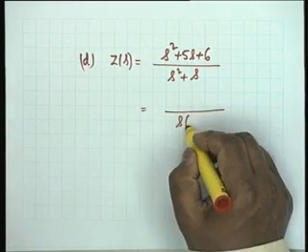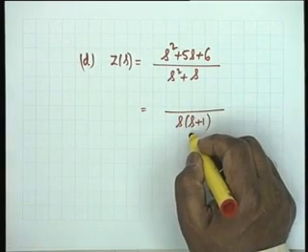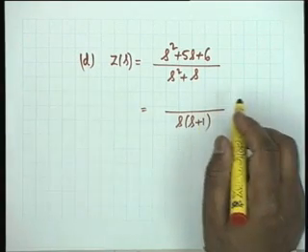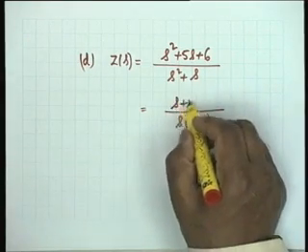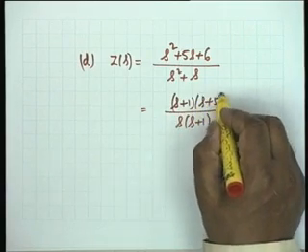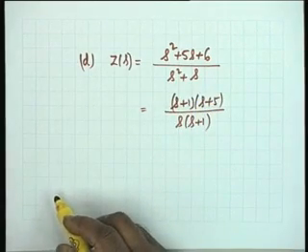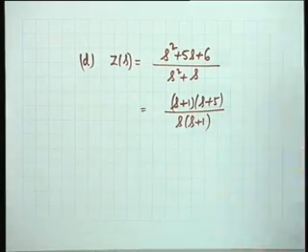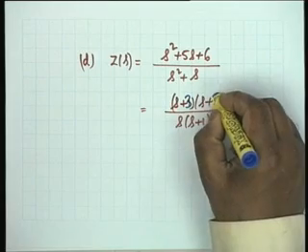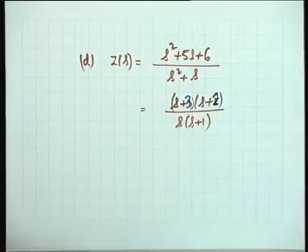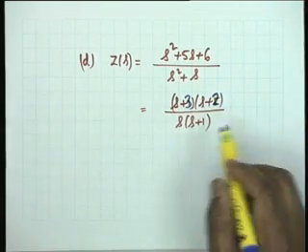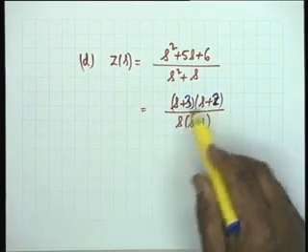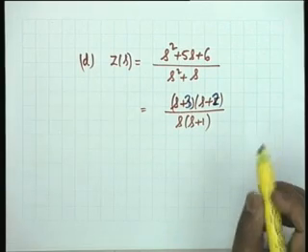Now as I said, the common sense. You notice that there is a cancellation. No further efforts are needed. You see, this is (s plus 1)(s plus 5)... oh, okay, there is no cancellation. (s plus 3) and (s plus 2). Now 0, 0, 1, 2, 3. No, poles and zeros do not alternate.